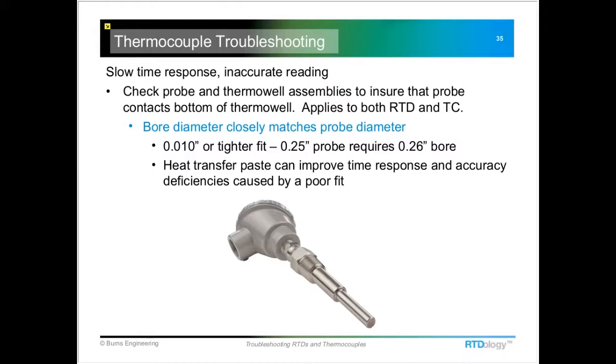And here you would need to make sure that when you put it in the well that it's only going down on the very tip, and it only covers about an inch, maybe an inch and a half of the temperature probe in the tip. You absolutely don't want it running all the way up inside here, because that's going to make your stem conduction and everything a little bit worse. It'll just nullify whatever you've tried to do down on the very tip of the thermal well.